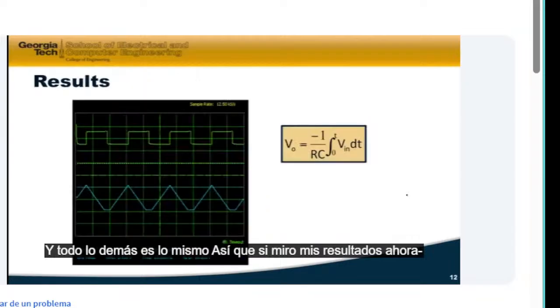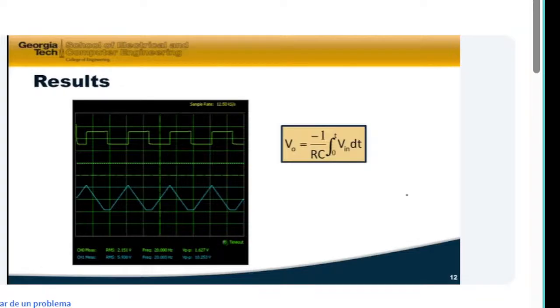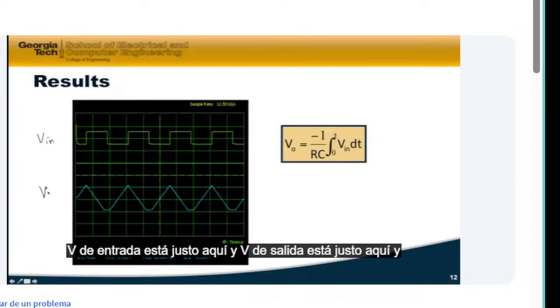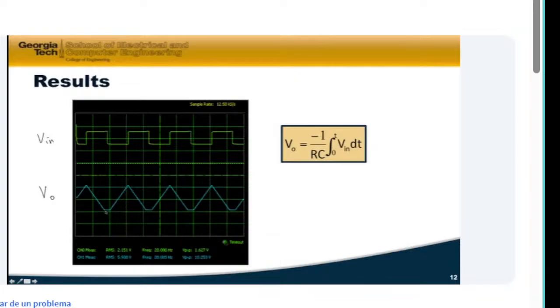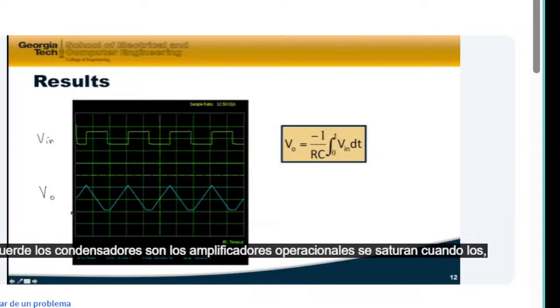So if I look at my results now, Vn is right here, and Vout is right here, and I'm integrating Vin to give me Vout. And I do have a little bit of clipping right here because it goes out of range. Remember, the op-amps will saturate when the...